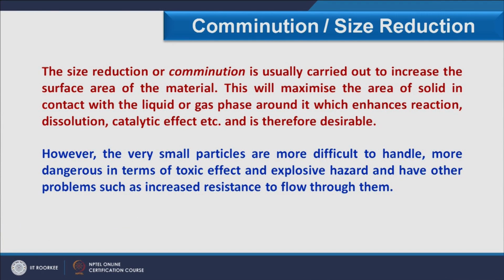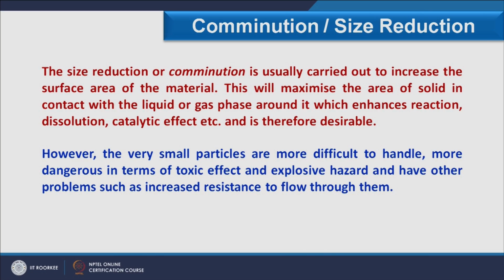However, the very small particles are more difficult to handle, more dangerous in terms of toxic effect as well as explosive hazard, and have other problems such as increased resistance to flow through them. So, when we have small particles, we have to design the equipment so that the flow of the small particles inside the equipment should not be blocked.